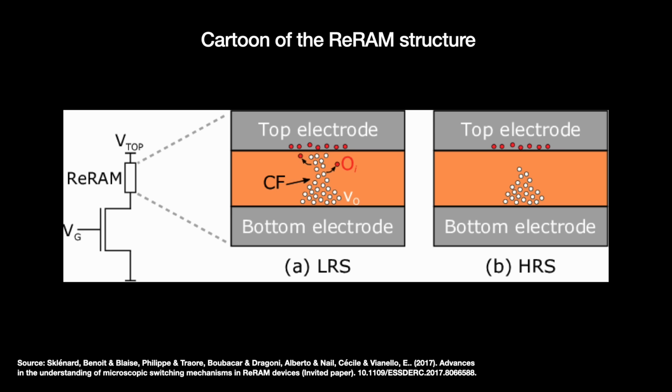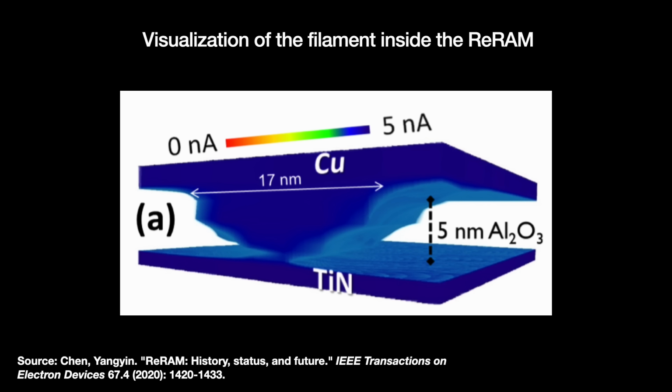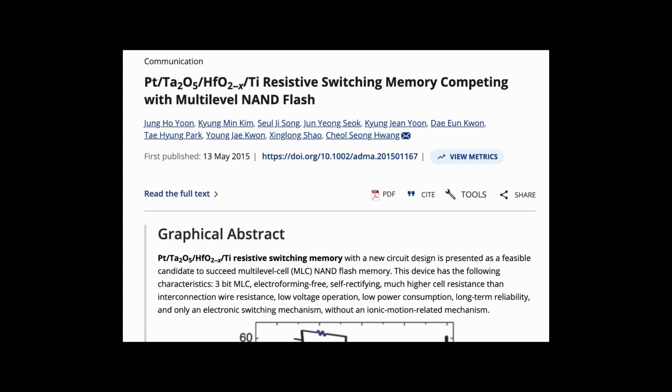On the other hand, there are some variability and endurance issues. The set and reset processes appear to be inherently random, leading to inconsistent behaviors, not what you want in a semiconductor technology. And I do wonder how many times we can make and break the filaments before it starts to exhibit weird behaviors. Broadly speaking, the technology has commercial potential, but it also feels like something that pops its head up every so often, attempting to ride the latest significant trend.